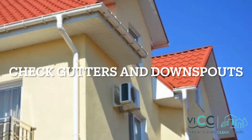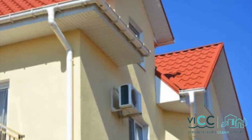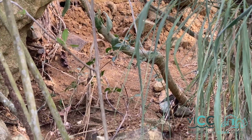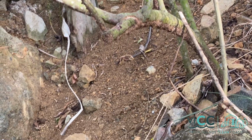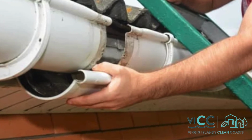Check gutters and downspouts. One of the first things you should do is check your gutters and downspouts and make sure that all the water is going into your cistern. Soggy and eroded areas near the foundation of your home can indicate that your gutters are clogged, pitched incorrectly, or undersized. Fix this simple problem and save money on more expensive solutions in the future.